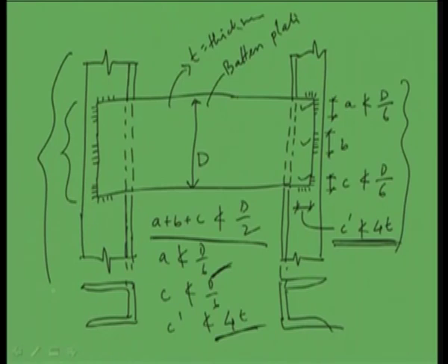And if we go for welding joint, then we have to see what length of weld is required for the forces coming into the picture. Then we have to maintain the codal provisions, that is, the distribution of the welding length, return weld, and lap length. All these things we have to decide as per the code provisions, and we have to see whether we are maintaining them or not. So, in this way we can design.